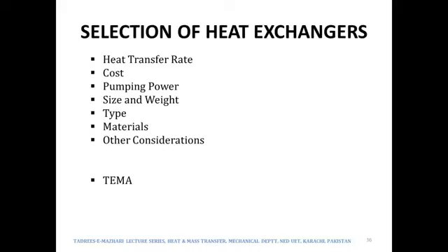And its cost plays a very important role, because in any business we need to know the B by C analysis, benefit to cost analysis, or the payback period, or other financial parameters. The pumping power is an important point, because the fluid will be made to flow through the tubes and through the shell. So therefore there would certainly be a requirement of pumping power of the fluids.